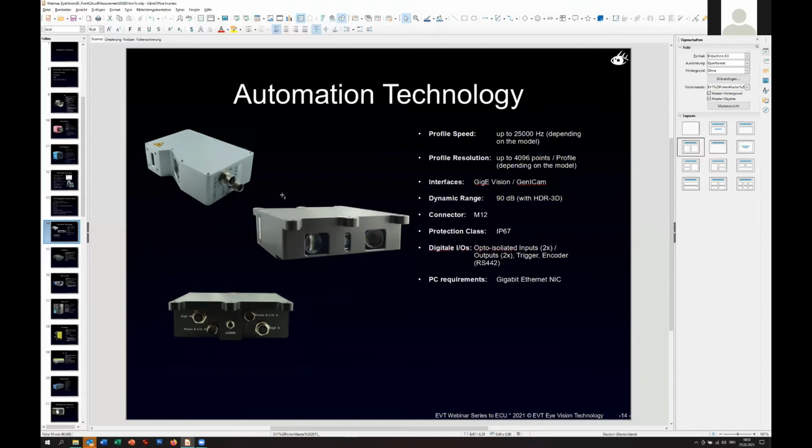without doing any calibration. Here is another option, which you get from most manufacturers. We don't have all the pictures, but in this case we have it. This is a dual camera version with a laser in the center. This has some advantages if you have very deep objects where one camera has shadowing, so you can use the other camera and combine these two point clouds into one point cloud, which eliminates this shadowing. The software supports it.